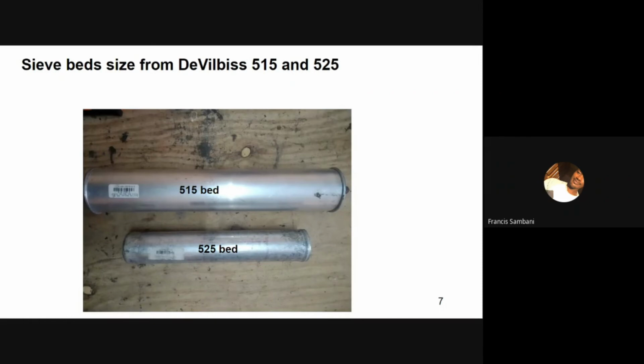Moving on, the demand increased for concentrators with flow rates greater than 5 liters per minute. That means as we needed more liters, for example 8 liters or 10 liters per minute, manufacturers chose to use the lithium-based zeolite in those models. If you wanted to get 10 liters with the sodium-based zeolite, you would need a much more powerful compressor and a much bigger sieve bed, reducing the portability of the machine.